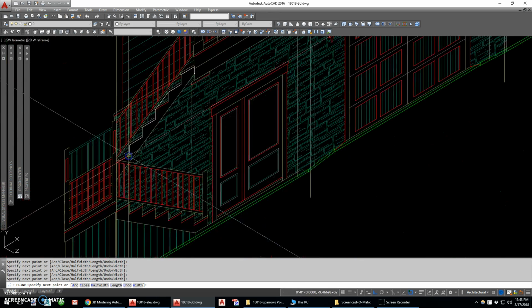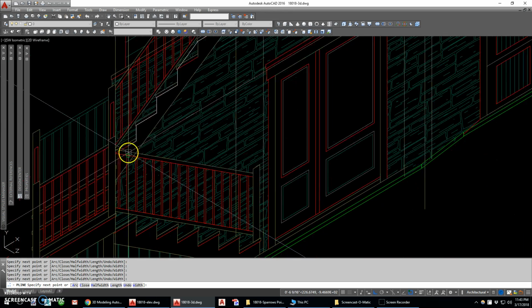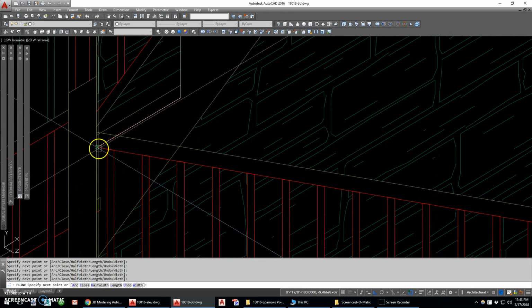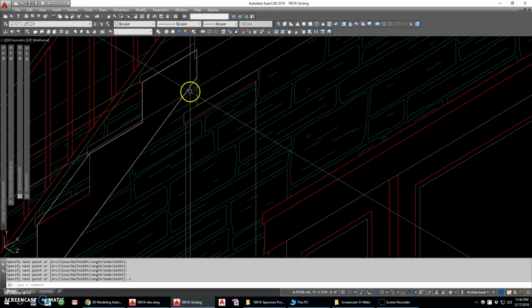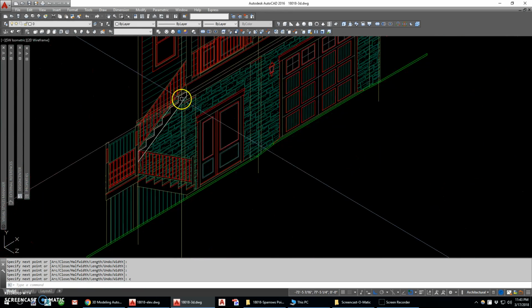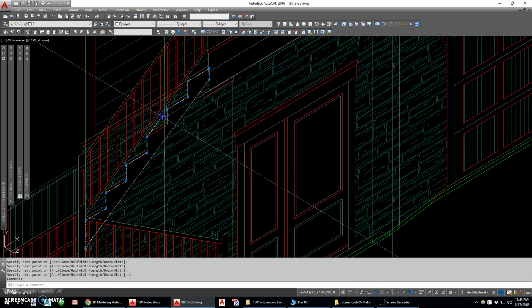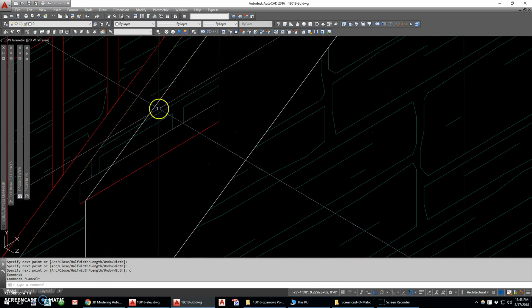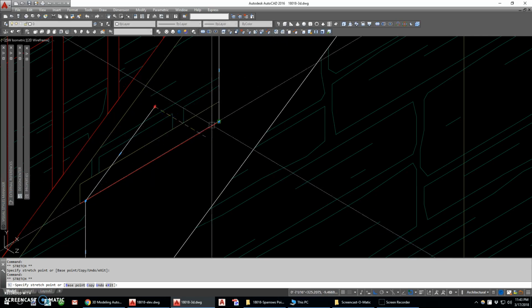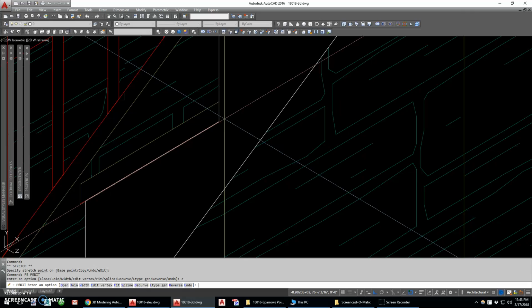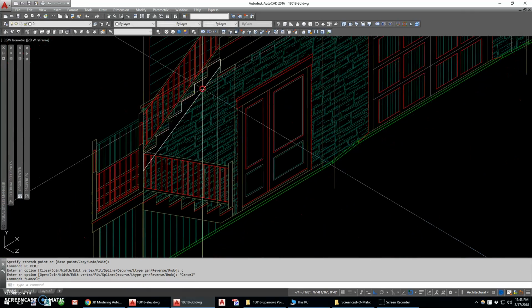And again, I'm making the stairs as solid. I realize that these would probably be stringers. We can hollow those out later and change them. But the profile is the same. It looks like I just messed that up. I'm going to break this polyline. Move my points down here. P-edit, close. So now I have the profile of stairs.